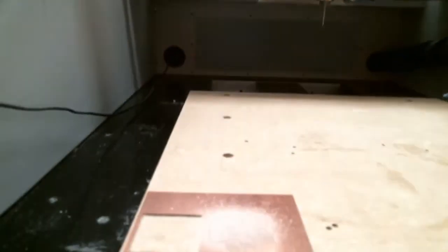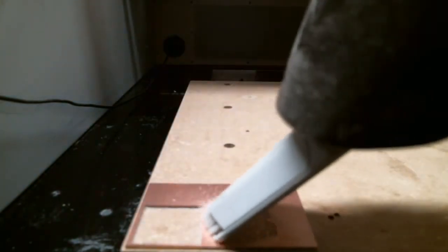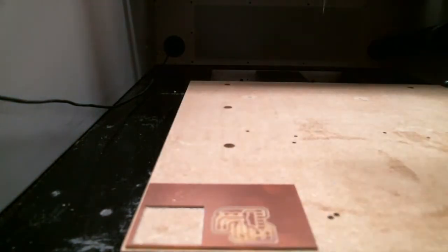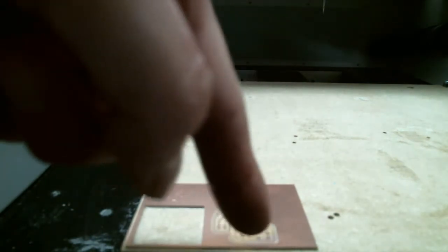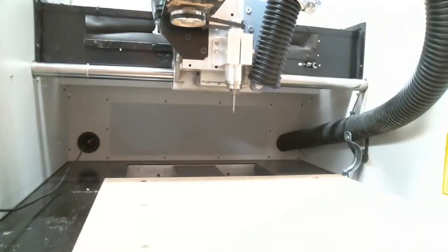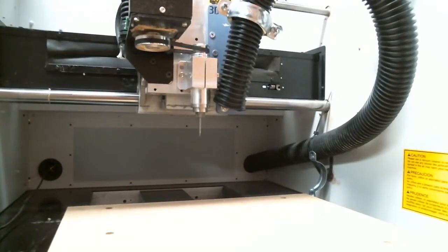so you can access it with your hands. So you open this up, zoom in here. As we can see, there are some parts that are not completely cut. That is probably because the surface is not completely even. We want to change the tool from 0.4 millimeters to 0.8 millimeters.